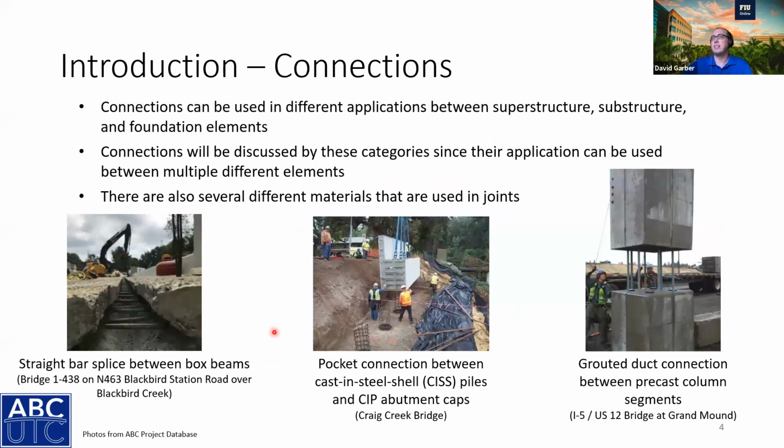Next, an introduction to connections. The connections can be used in many different applications between different superstructure, substructure, and foundation elements. I'm just highlighting some of the common or previously used connection details. One common detail is between different prefabricated superstructure elements. So these are adjacent box beams with a UHPC straight bar splice connection. This is a pocket connection and a grouted duct connection. So see the straight bars going into small little duct connectors in the top element.